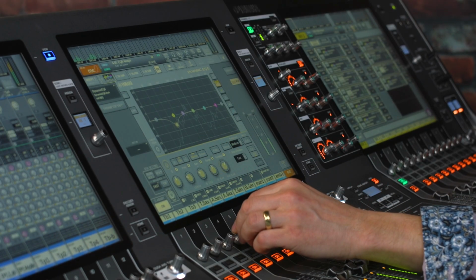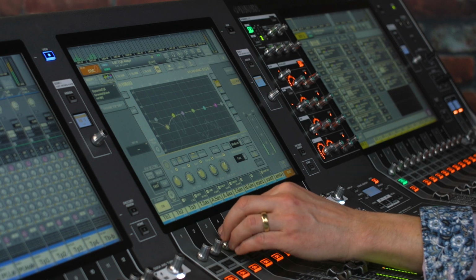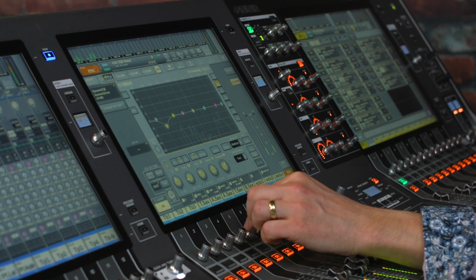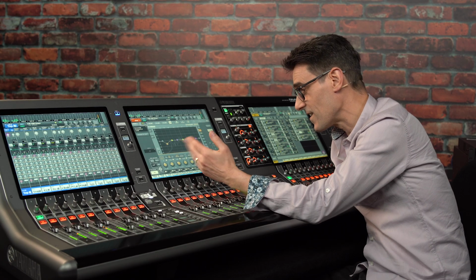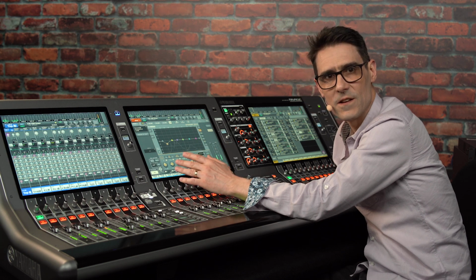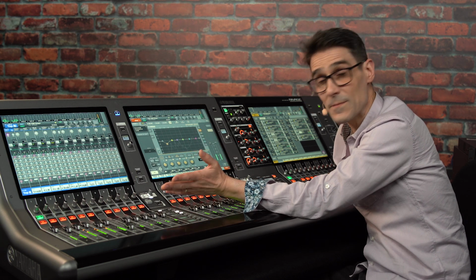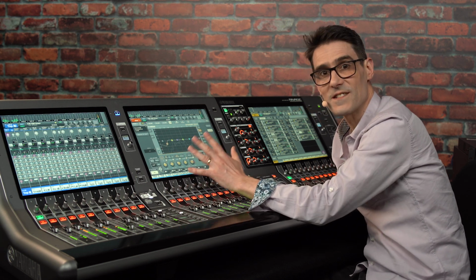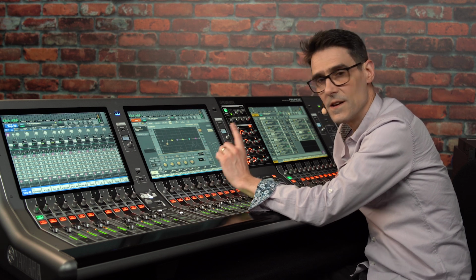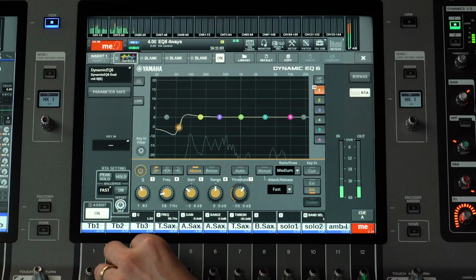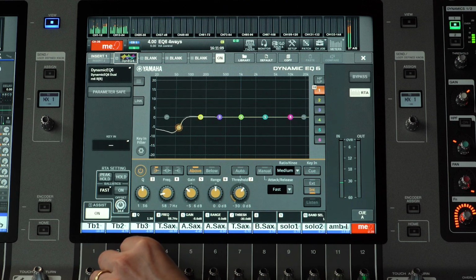If you limit yourself to the frequency, Q, and gain parameters, it will operate just like a regular parametric EQ. In a similar way to the precise EQ in the channel strips, the Q parameter is available on a shelf to vary the slope or overshoot.